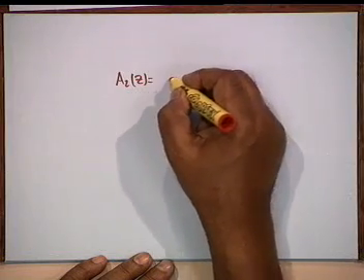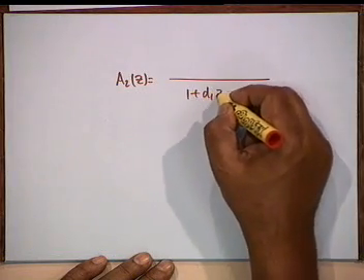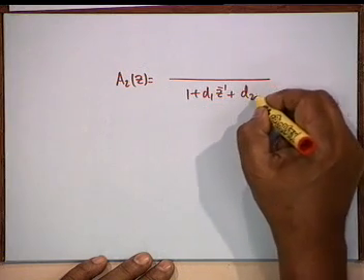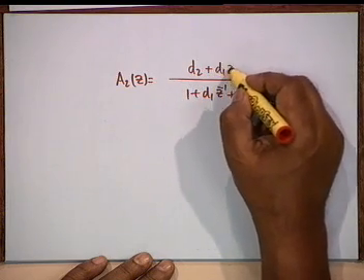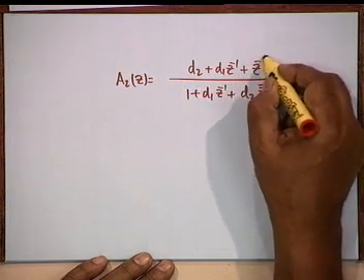No, not quite, because the coefficient of z to the minus 2 in the denominator is d1 d2, whereas your multiplier is d2. So it's an indirect, but it doesn't matter. We have been able to do it with 2 multipliers. Now one might ask, why didn't you take the usual form, that is 1 plus d1 z inverse plus d2 z to the minus 2, then d2 plus d1 z inverse plus z to the minus 2? Why didn't you take this form?